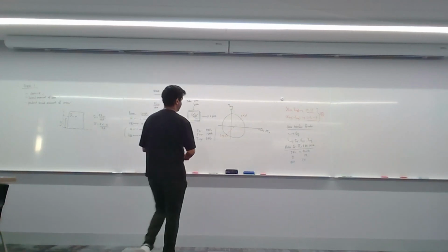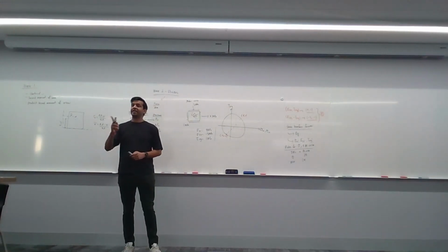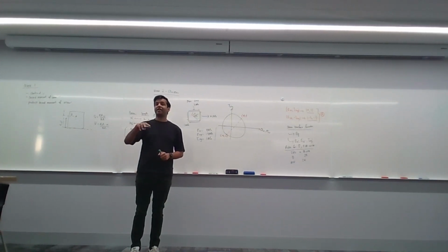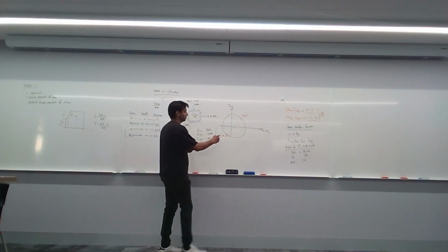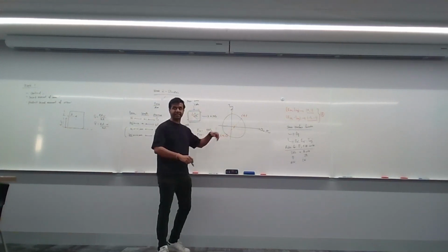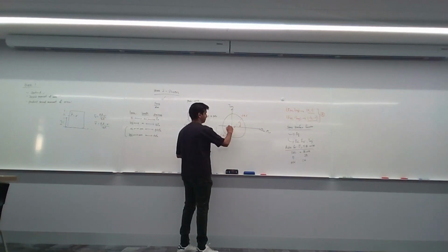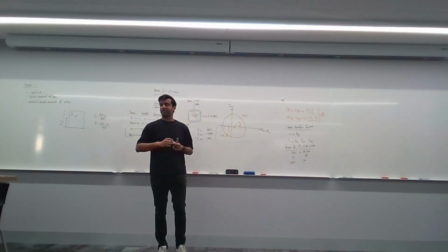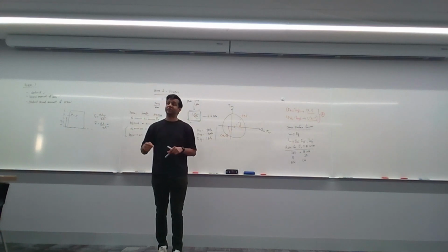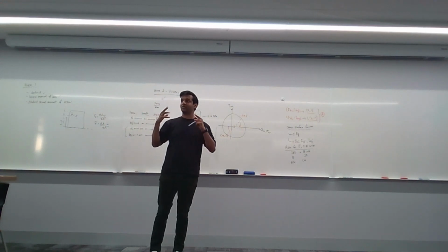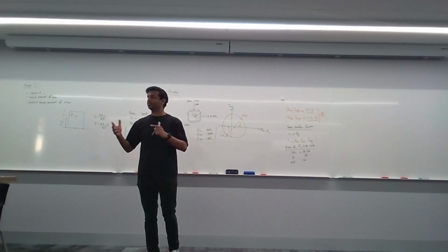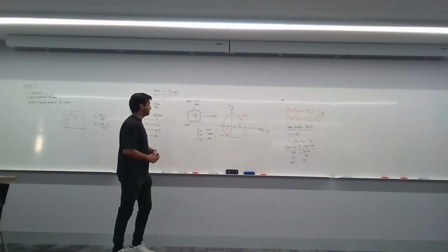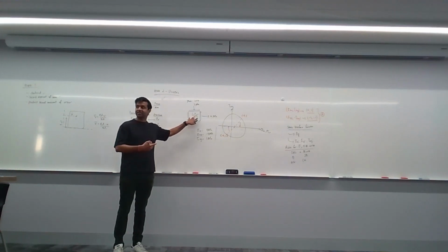Okay. Alright. Look, the question is you've got to ask yourself, in the Mohr circle, how did you rotate to get to the principal state? In the Mohr circle, to get to the principal state, which is on the x-axis, you had to rotate this way. So you rotated clockwise to get to the principal state in the Mohr circle, which means in real life your axis rotated anti-clockwise by half the angle to get to the principal state. Which means it's more likely that the red axis is the correct one as opposed to the green one.